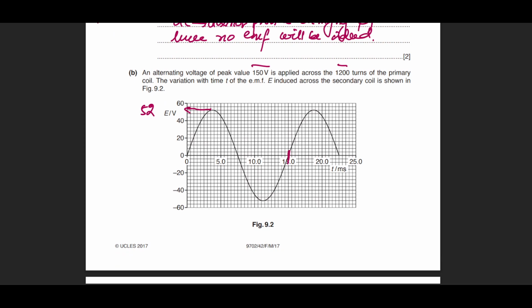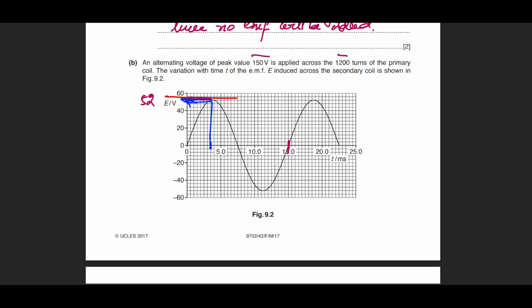At this point, we see that the voltage is changing at all times. You can see over here that the peak value that we almost approach is happening at somewhat less than 5 milliseconds. Now, notice that when the voltage is maximum, that means that the flux has already reached its maximum value. The maximum changing voltage we observe is actually at the gradient function over here.